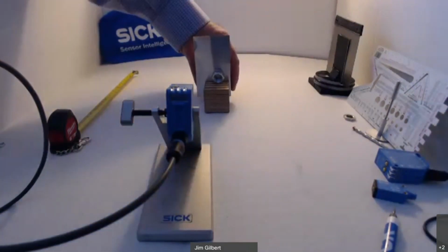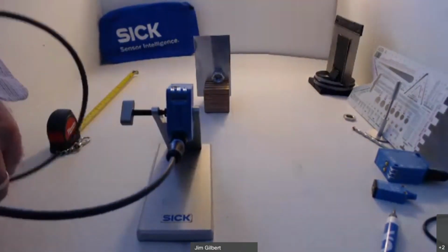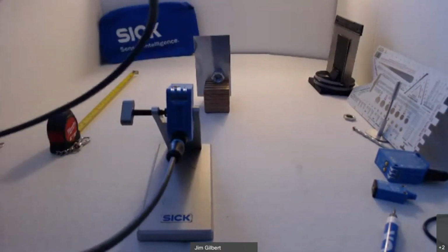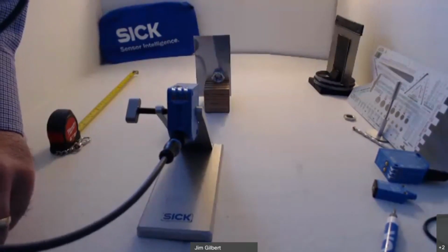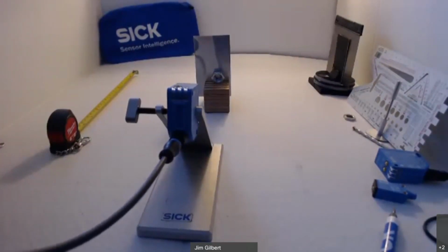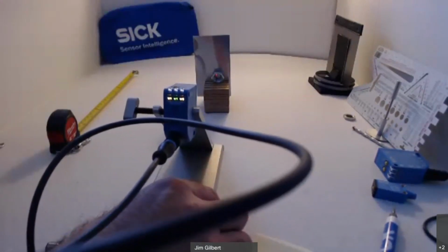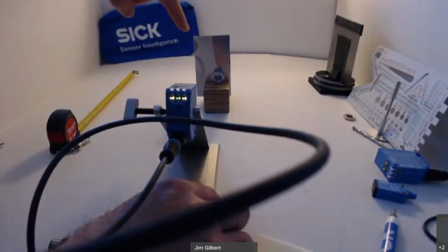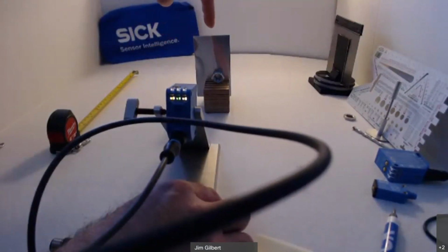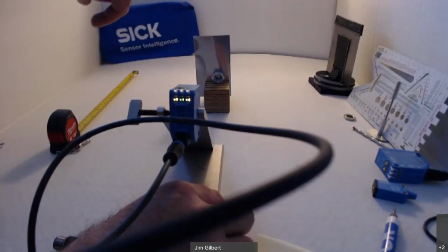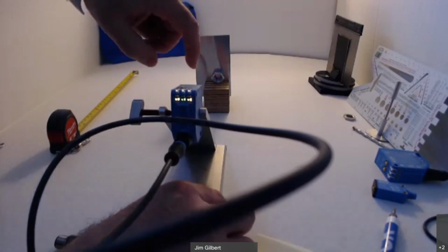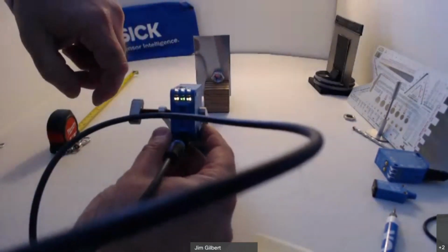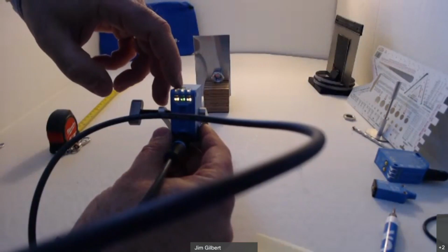So imagine this was going into a work cell and it needed to be welded in place by a robot assembly. In this case, I'll switch over to a different power supply. The name of the game here is to see the nut and not the background that it sits on. So I'm going to position the sensor so the laser is on my target, and I'm going to teach it to the PEM nut.